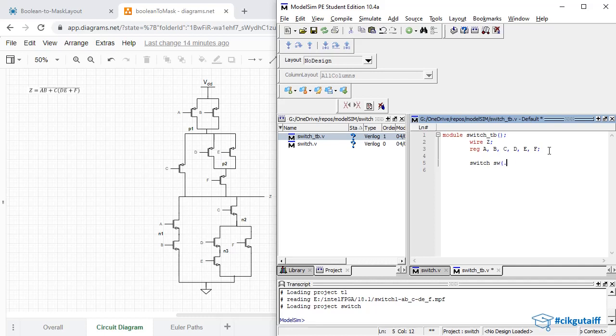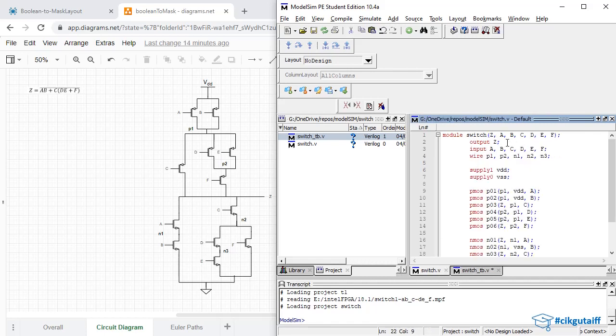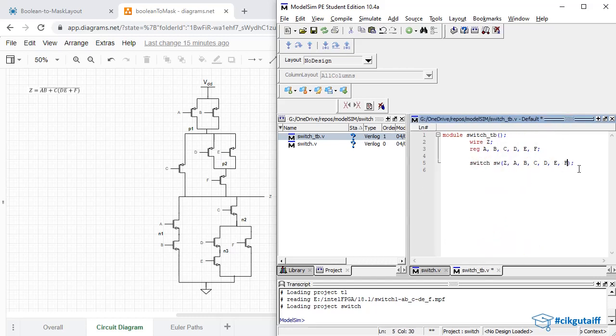And then because I'm using the same signal letters and all of the same case, when I'm defining the parameter, I can just simply say dot asterisk. Otherwise I need to do something like this, where the list matches with the module definition that I had earlier. So this is the module parameter definition, and in my test bench I would have to do the same. But if the signals are all of the same case and same spelling, then this is a short form. I just say dot star, and it'll work exactly the same way.